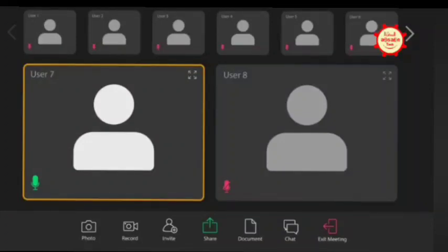I have some issues. For sour service, generally we do the NACE certification as per NACE MR0103 or the other one, MR0175. Actually, it was not clearly stated in which case we need to do the HIC testing. I think, as far as I know, it will generally be given by the licensor based on his past experience. Can anybody give more insight on that: in which case HIC falls for HIC testing?